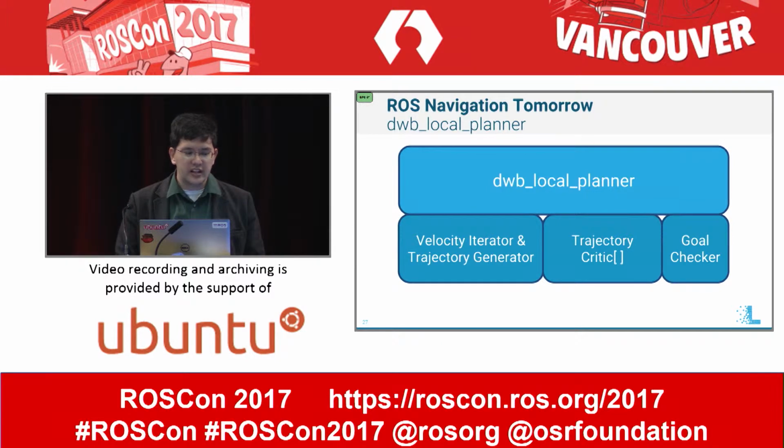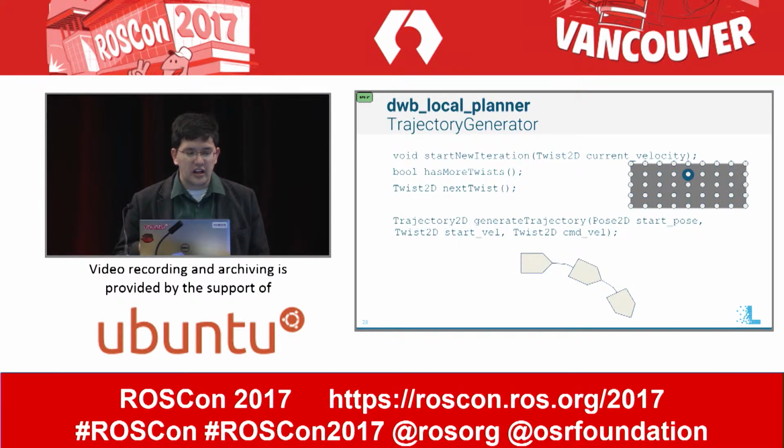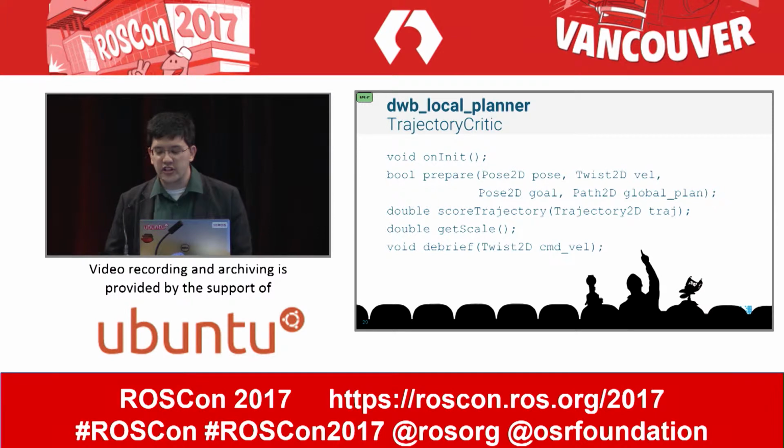And so in that first bit, we have the trajectory generation. So we have a standard iterator interface for iterating through the different velocities, and you feed in the current velocity there. We have the function for generating the trajectory that takes the start pose, start velocity, and command velocity. And then we have all the trajectory critics, people who, or things that will critique the trajectories.